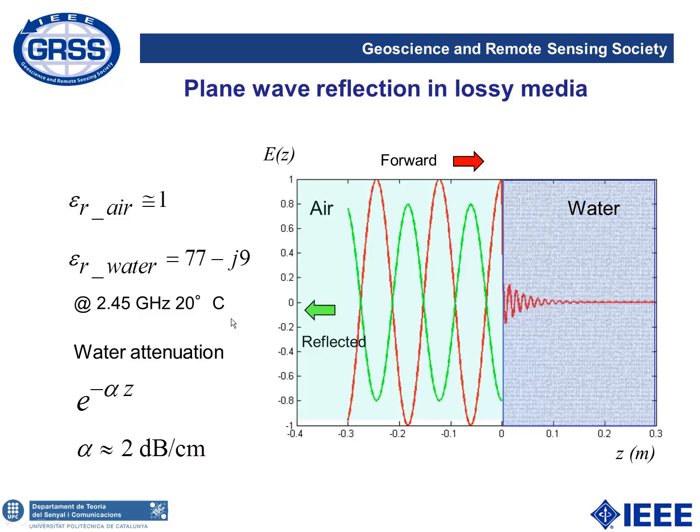This corresponds to a 2.45 GHz microwave region, by the way. And what happens? We have a lot of contrast. The impedance of both mediums is going to be very different, and if the impedances are different, we have a strong reflection. And actually this green line here is showing the amplitude of the reflected wave. You see the amplitude is not the original one, but is almost 0.8, so it's very important. The reflection coefficient is approximately 0.8.